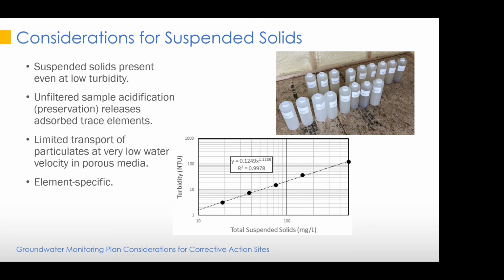That series of pictures in the upper right corner shows water from a single monitoring well that was pumped over time. And each of those containers represents an equilibrium condition where you're measuring the field parameters, and the field parameters have stabilized, and you get your sample.